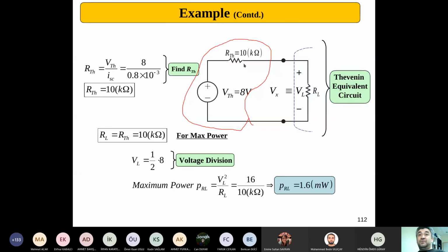And to find the maximum power transfer, just that's VTH squared by, there has to be a 4 in here. I probably missed the 4 in here. So this is 40, this is 0.4 milliwatts. Oh, sorry. There has to be a 4 here, but 4 is also divided in here. The answer is correct. It is 8 squared, 64, divided by that will give me 16. There's a 4 missing in here, nothing else. The rest of them is true. It's correct, sorry.